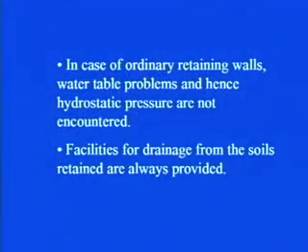So, the backfill material you will be knowing beforehand, before going for the construction. Obviously, that soil you are retaining, so you know about that particular soil, what type of soil it is, and then accordingly from these guidelines you can pick the value of delta and go ahead in the design procedure. Now, in case of ordinary retaining walls, water table problems and hence hydrostatic pressure are not encountered.